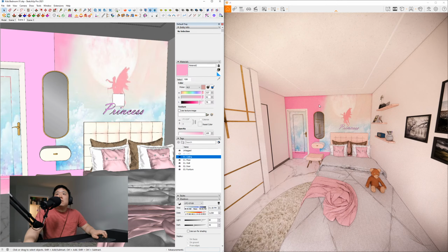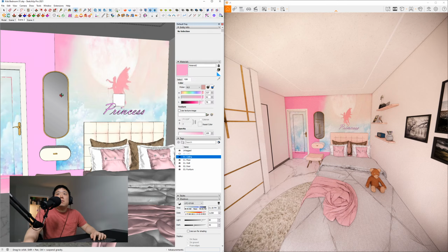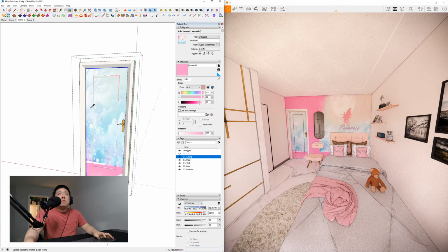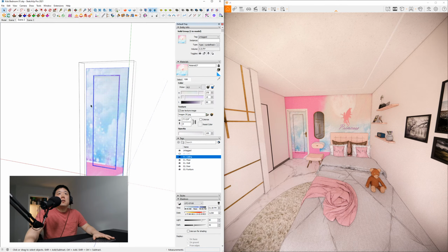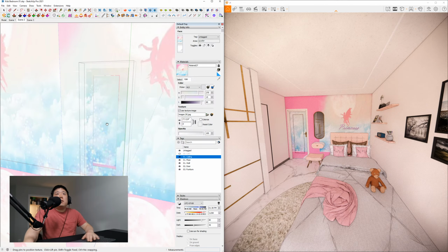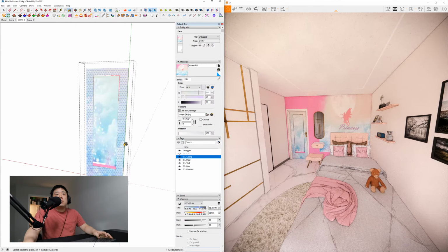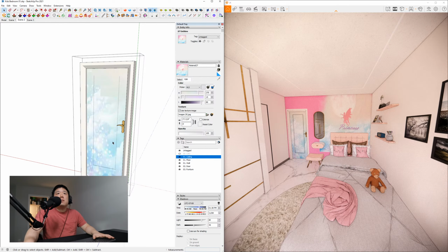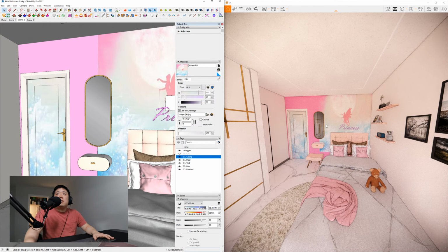You can at least hide it up here, and then maybe the door, if you want to avoid this sort of seam here, you can reposition the image specific to the door, so that it is not at least repeating in the middle of the door. So once you position that, sample that, and then select all, and then just paint on top, and you'll see how that positioning applies to the entire door. So that looks somewhat better in terms of positioning.